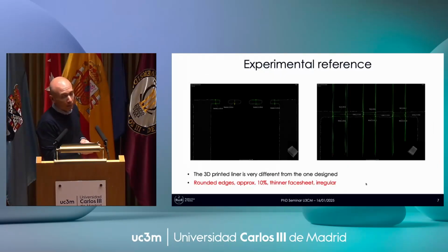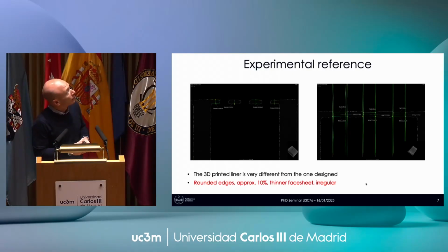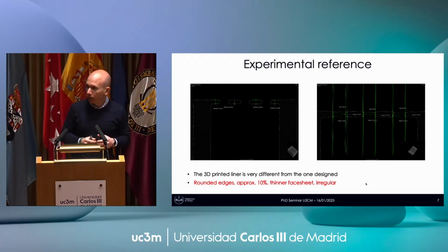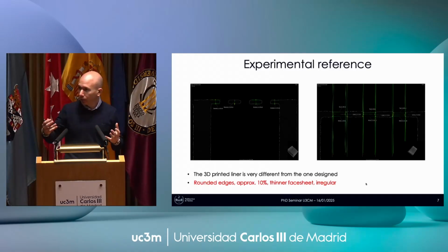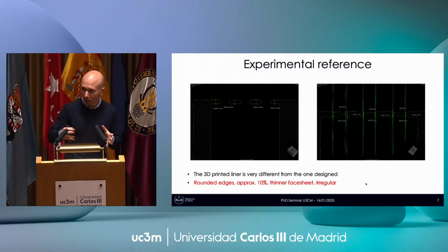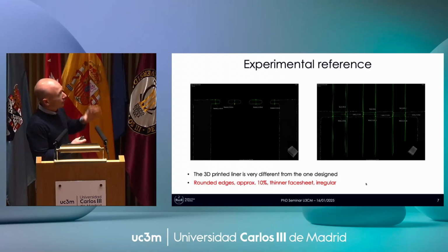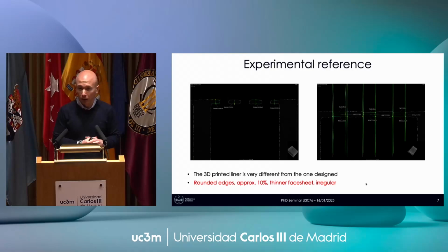However, after about 1 year of unsuccessful numerical simulations, we decided to look at what was actually built. It came out that the geometry we wished to have was very different from the one that we actually tested. This caused large mismatches between numerical simulations and experiments, and then we took a scan of about 50 different orifices over different cavities. We did this work both using the sample that was tested at NASA and the sample that was tested in Brazil.